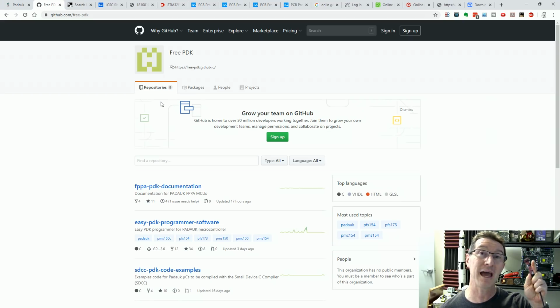Then the video after that is programming the blank Atmel micro on here, not using an Atmel programmer, but using the USB port, using the USB serial bootloader that's burnt into the silicon of the Atmel microcontroller. It's called DFU, or device firmware update mode.